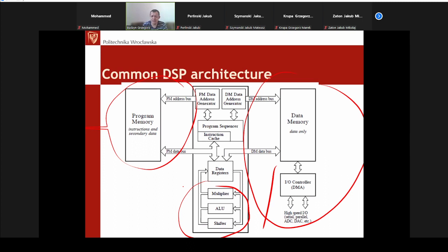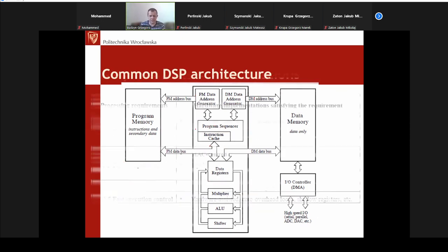These are as well the kind of multipliers and dividers. And for the same purpose of improving the performance of the DSP itself, caches are not unusual. Not unusual here is the instruction cache, but the data cache is not something present quite often in microcontrollers.